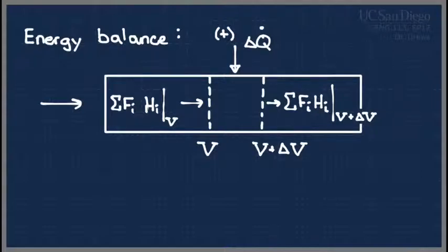As long as you know your enthalpies as something like joules per mole of whatever species you're doing, you multiply it by the molar flow rate, and that's the amount of energy that's being dumped into your system just because there's flow coming in and out. The only one that we have to fiddle with a lot is the enthalpy term. All the fiddling that we had to do with the enthalpy term for the batch reactor is the same fiddling that we have to do here. So I'll present those steps. We're just not going to go through the algebra of actually substituting them in and rearranging like we did for the batch reactor.